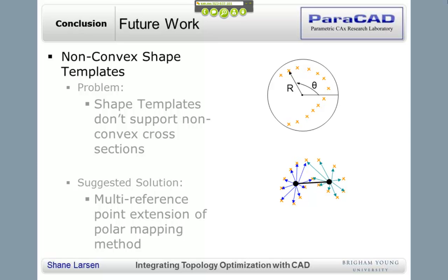Okay. Do you know anything about the forces in HyperMesh? Like what units? So HyperMesh is unitless, and so you need to make sure that when you go in there and set up your lengths, widths, heights, loads, things like that, that you are consistent in what you're giving to it. So if we say a load of 1,000, do we have any idea, like, does that relate to a Newton or something? Okay.